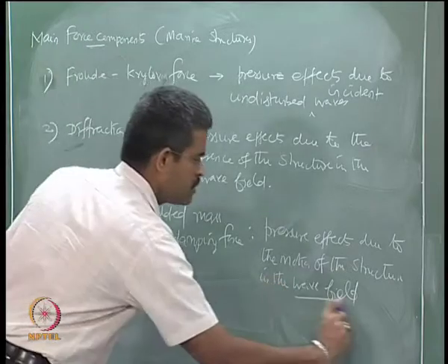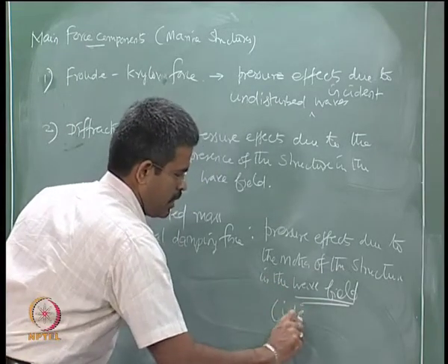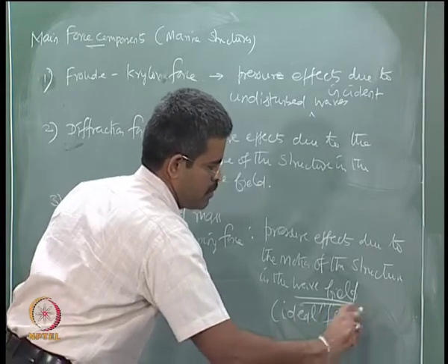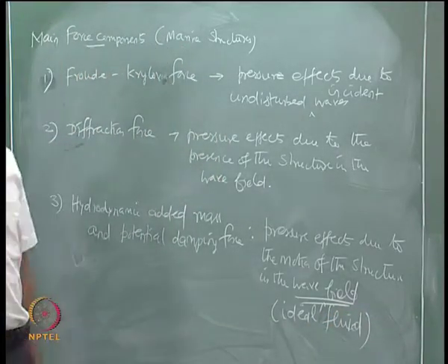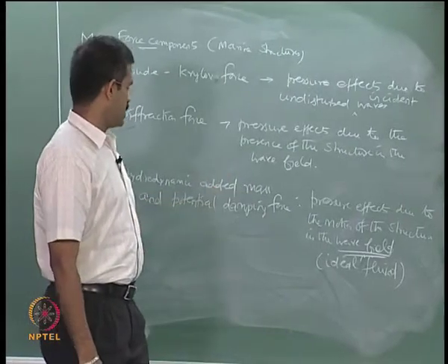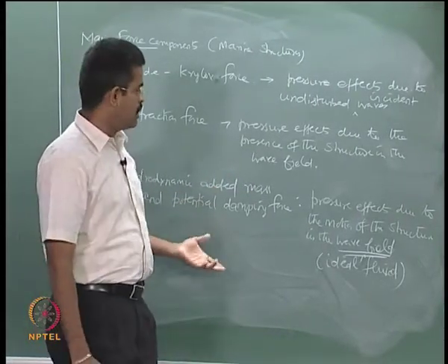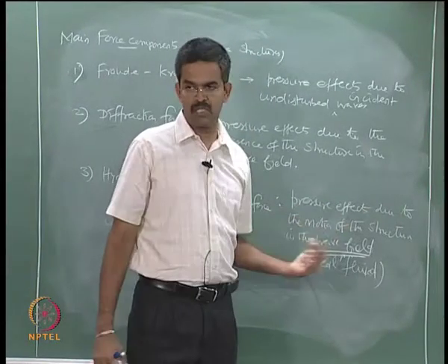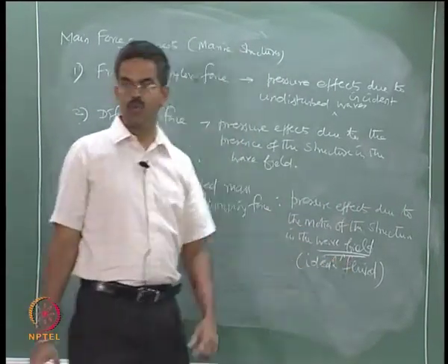We consider the wave field as an ideal fluid, and therefore we say the hydrodynamic added mass and the potential damping force are consequences of the pressure effects caused due to the motion of the structure in the ideal fluid.